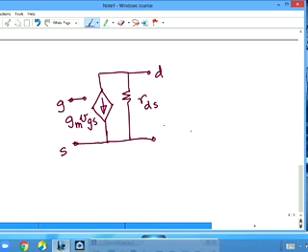All the other components remain just as they are. And now your circuit has become a linear circuit because you're analyzing the circuit only incrementally. If I make a small change at the input, what is the incremental current consumed? If I make a small change in the input, what is the incremental change at the output? As far as that is concerned, the circuit is linear because all the components are linear.